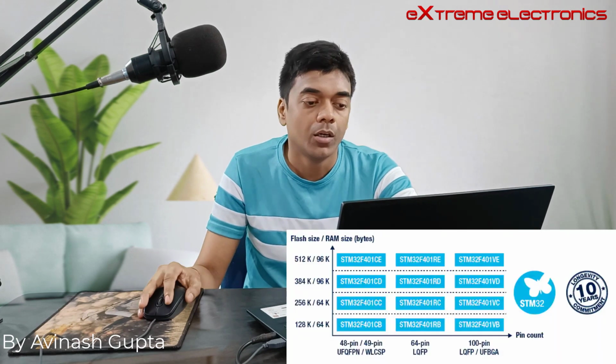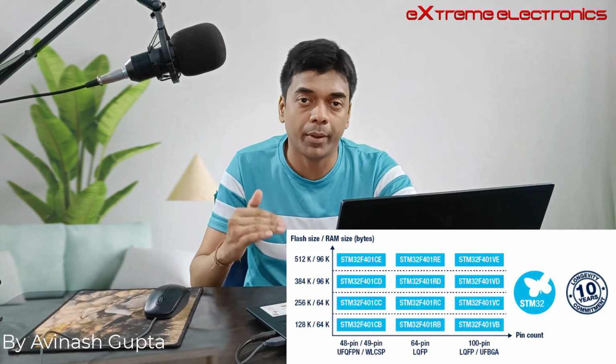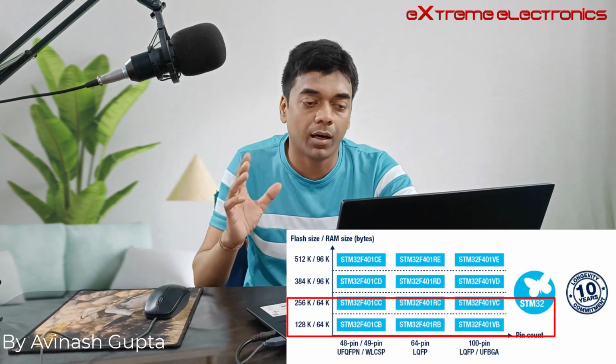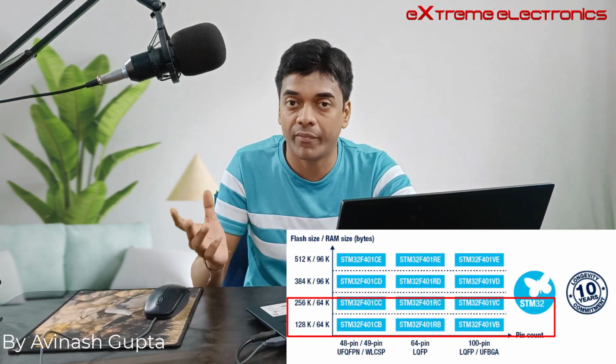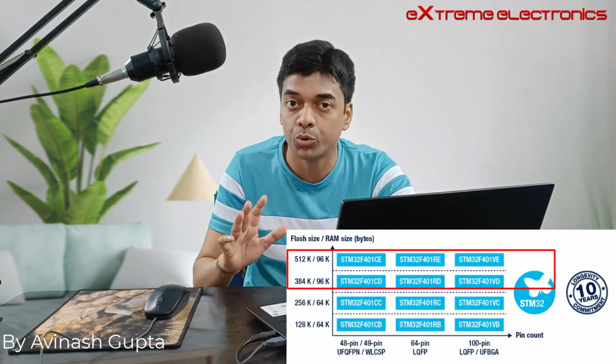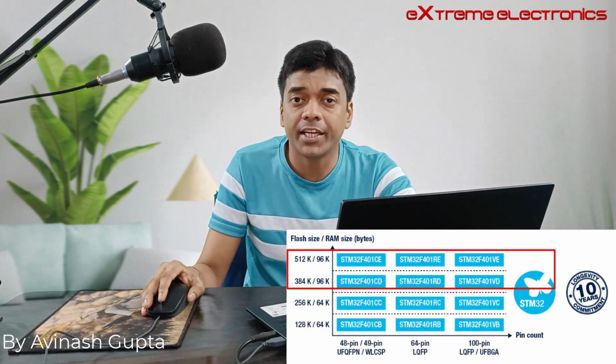So the first thing you must do in order to understand this chip is download the datasheet of this microcontroller. That is the STM32F401 microcontroller's datasheet. And on ST's website, you will find two datasheets for the different variants of this microcontroller. One is for the lower memory group and one is for the higher memory group. One datasheet covers the 128 kilobyte and 256 kilobyte variants, while the other datasheet covers the 384 kilobyte and 512 kilobyte variants. So you should download both of the datasheets and then study them. And from the datasheet, we should gather some key information and note it down.